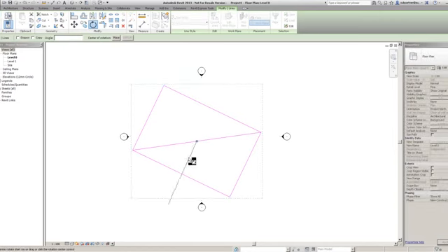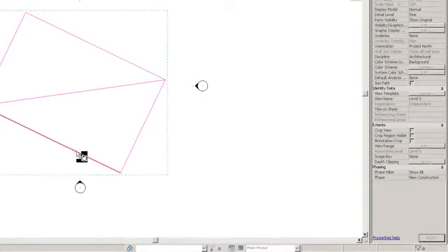Okay. Now this pivot point, this base point, isn't basically constrained and locked in the middle of this geometry. That's just the default of where it goes. So what I'm going to do, if I hover over it, you can see how my reference line disappears. That's because now what I can do is I can simply left click and drag and place that anywhere I want. Okay, I just snapped it to that corner. And what we can do, because Revit asks you for your first point of reference, how polite, okay, we can simply just click that line just there and choose that to be our first line of reference.